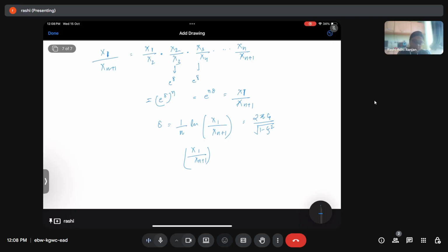Once we get the model, then we have to find out the parameter values. And using these techniques, like the concept of logarithmic decrement, we can find out the values of eta, omega d, and omega n, put them into the equation, and then simulate it for different kinds of inputs, conditions, and forcing, in order to understand how the system is going to behave.